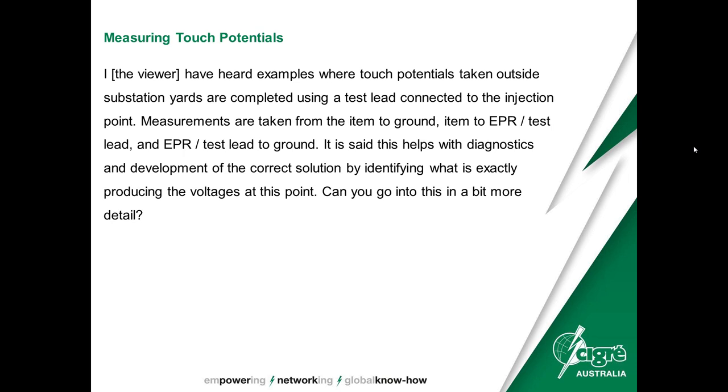If it was a transfer out from the substation, then the best mitigation, almost a primary mitigation, is to create disconnection between the fence and the substation. Now it doesn't have to be physically connected, it could be soil coupled transfer, it could be current that's gone into the ground and popped up into the fence close to the substation, or it could be inadvertent or deliberate direct bonds. So there's options there to separate it. If the fence transfer is in from remotely, then the better option is to go further away from the substation and create some additional earthing or some separation points in that fence away.